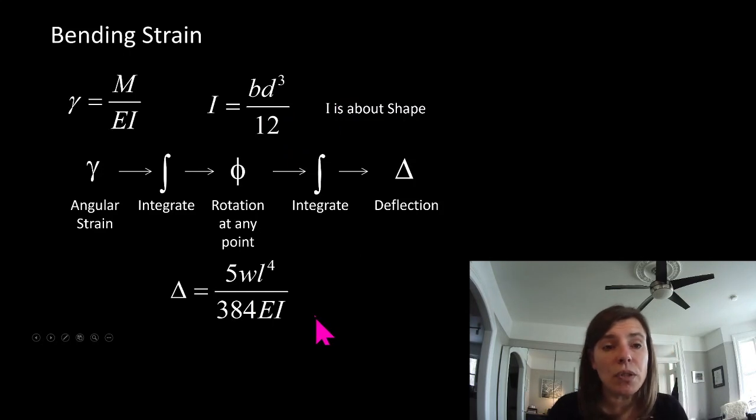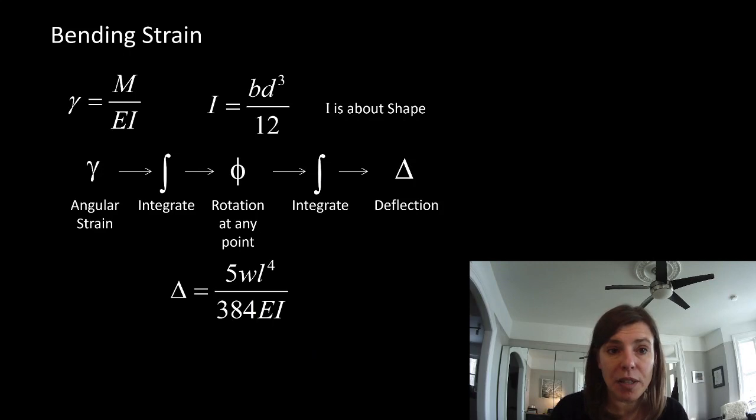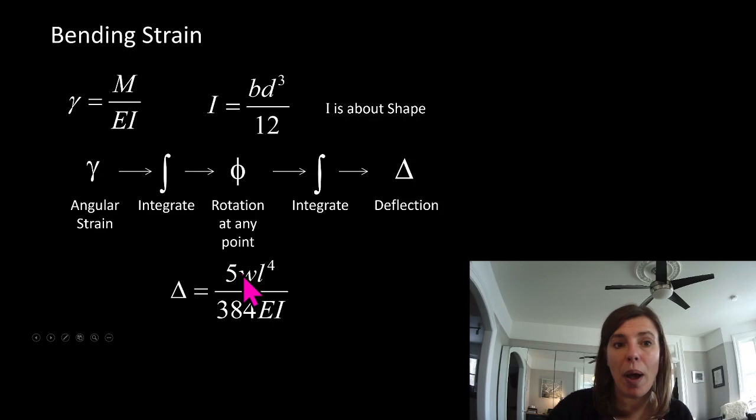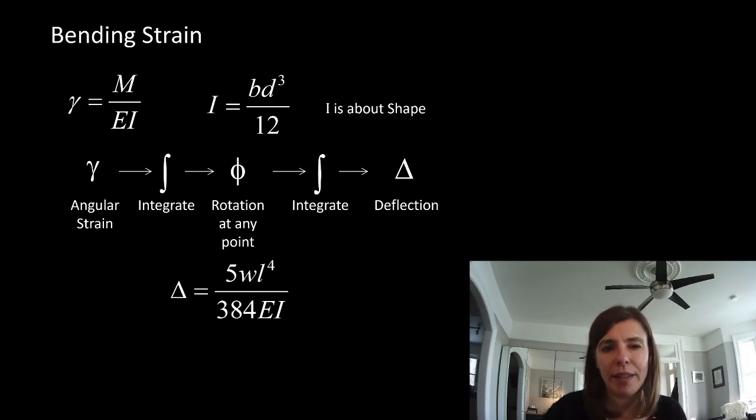So similar to our moment calculations that we've done in the past, we did this last term, we figured out the serviceability W. So for moment and shear, we were using WF, but remember I told you to always calculate W as well, or the serviceability, so W for dead and snow, or W for dead and live, and then W for live and W for snow as well.